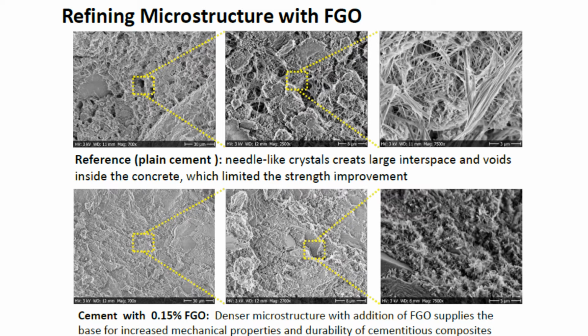And also one point is very crucial that we should keep in mind: we need a very low percentage of this graphene oxide. So it is also a very cost-effective and economic solution. Less than a percent, 0.158%, is enough to get an improvement in mechanical properties like flexural modulus and tensile strength.